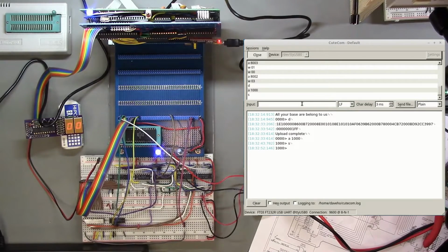All right, so at this point, nothing is happening because the mask register is set to hex FF, so every interrupt is basically blocked by the mask register, and also the CPU condition code register bit 4 is set to 1 so that the IRQ input on the CPU is also being ignored currently. All right, so let's change the mask register value to F7, so that will set bit 3 corresponding to IRQ3 in the mask register to 0, allowing IRQ3 to be generated.